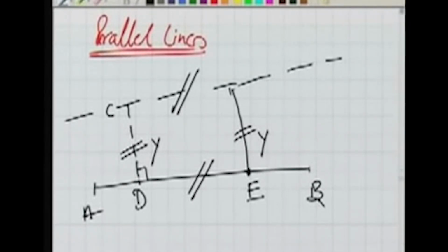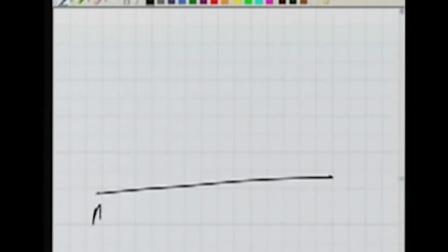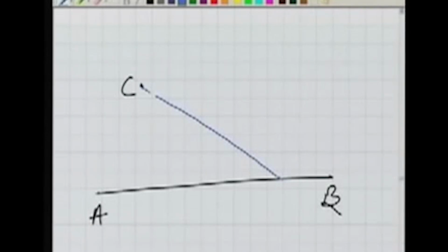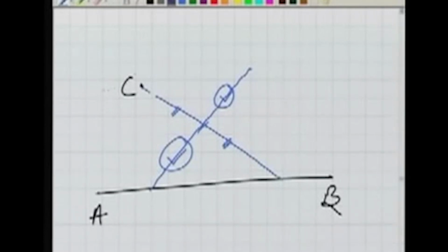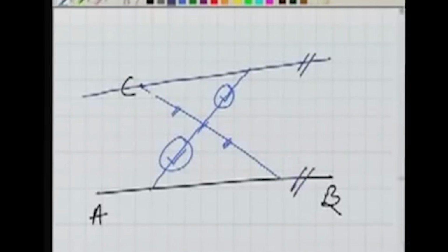There could be many other methods. Now your line AB, that's the point C. Take any line. If you can't drop the perpendiculars, take any other line. For example, let's say I'm showing this construction by blue lines. Any line, find its middle point. So these two are equal. Now from this middle point, join any point here, and whatever is this amount, extend this line by the same amount. So these two are equal. This part and this part are equal. If that is so, then the line joining these 2 points will be parallel to our line AB.